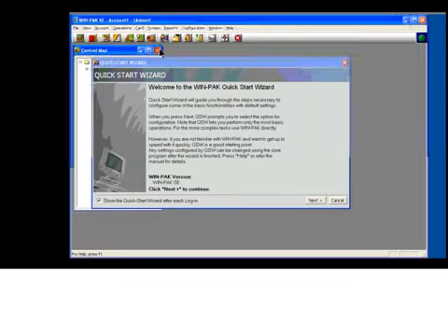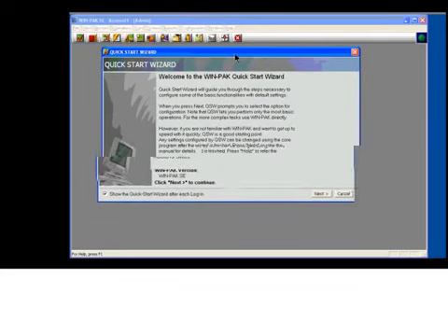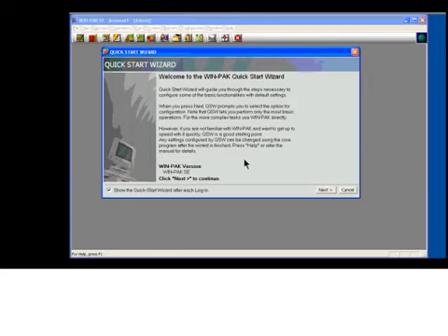On initial installation, the first thing that happens is the Quick Start Wizard pops up. The Quick Start Wizard gives us the capabilities of literally building a basic system. Using the Quick Start Wizard, you can generally get about 15 minutes or so, and you should have your first panel set up and running. So what we're going to do is use our Quick Start Wizard to build a basic system. We've got an NS2 Plus panel connected over an Ethernet connection. So what we're going to do is walk through the process. We click on the word Next,